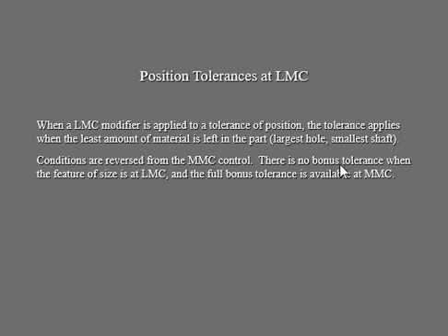Okay. People kind of get the hole and the relationship with the material, but they always have an issue with a small shaft. Okay, don't worry about it. If you have the largest hole, meaning you have the least material on that part, okay, since you have the least material on the part, you're going to have the smallest shaft because you are not dealing with the material only. What we're concentrating on here is your tolerance. Tolerance is a separate zone. That's why you have the smallest shaft.